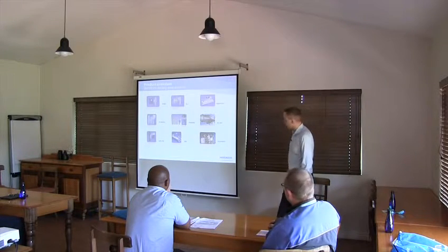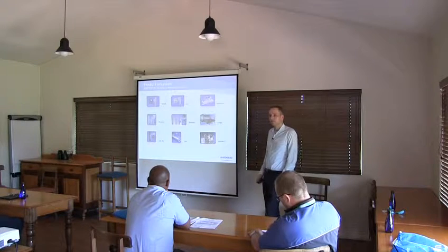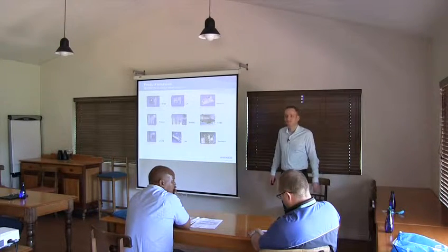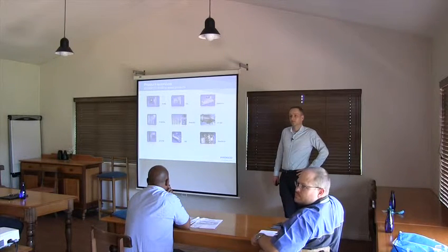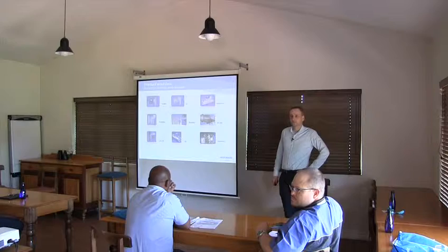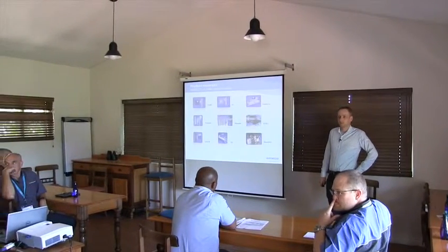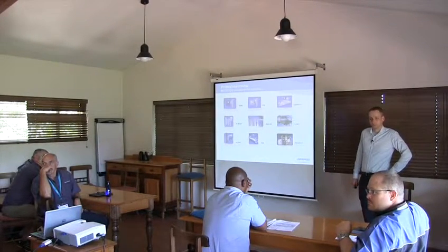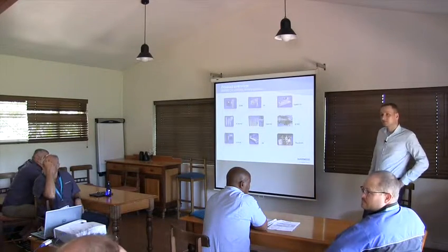Yeah. So typically we have sand filtration in front of drinking water systems. For households, if you take water from a borehole or from a water source like a dam close to your house, you put it through a cartridge filter, probably a 50 micron filter or something. And then you put it through the UV and it's drinking water. It's better than the stuff that you probably get out of the tap. Just keep in mind that it always needs to be filtered.